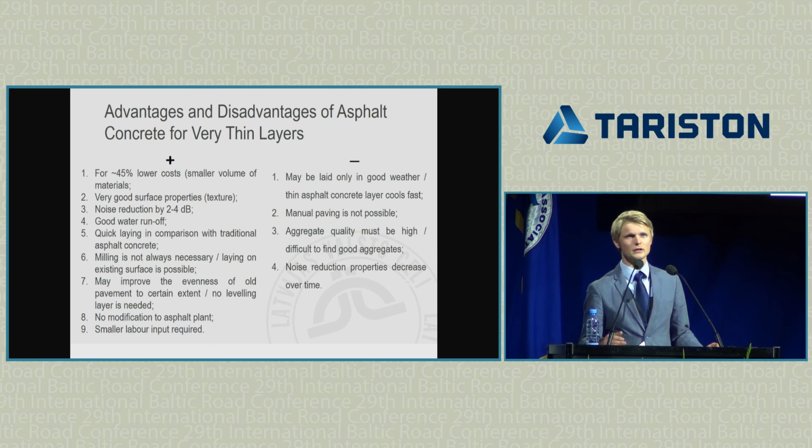Disadvantages: may be laid only in good weather because thin layer cools fast. Manual paving is not possible in good quality, of course, and aggregate quality must be high. And the last one, noise reduction decreases over time.